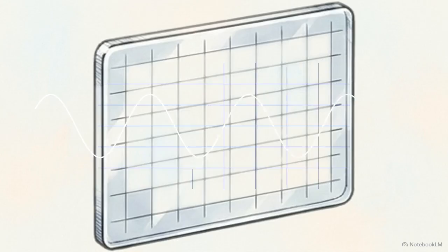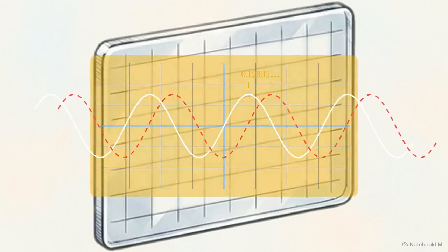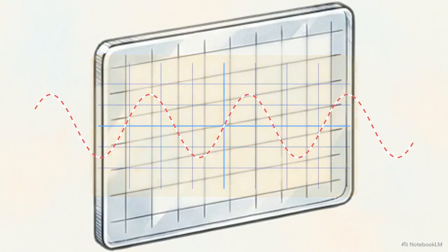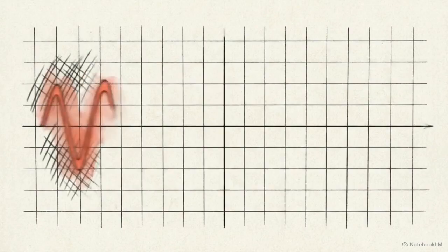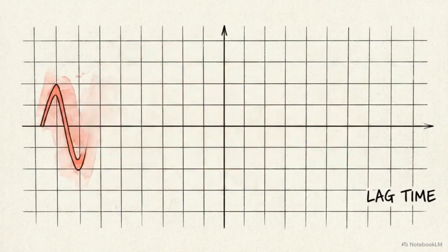In a legacy PLL, if a signal drifts out of phase, the hardware has to calculate the exact fractional time delay and then slowly ramp up a voltage to help the signal catch back up. That process takes time. Pushing the oscillators slowly back into alignment inherently introduces lag and jitter into the loop.